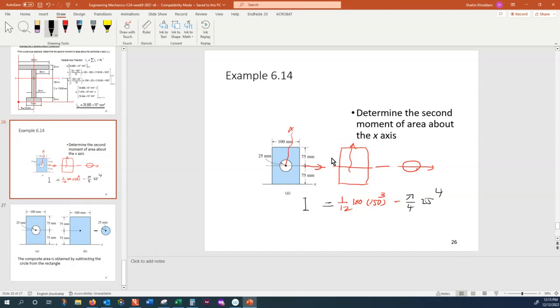All right, so today in summary, we went through deriving the internal forces in different beam examples. We did that through correlating distributed load w of x, shearing force V of x, and bending moment M of x. We solved a number of examples for that. And then we started performance analysis. We know that a beam performance is not only dictated by the internal load, but also by some geometrical terms like centroid and second moment of inertia.